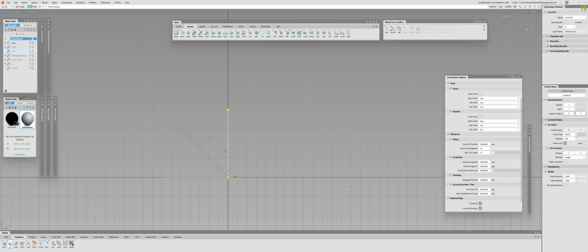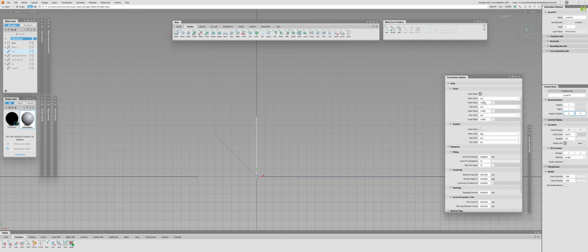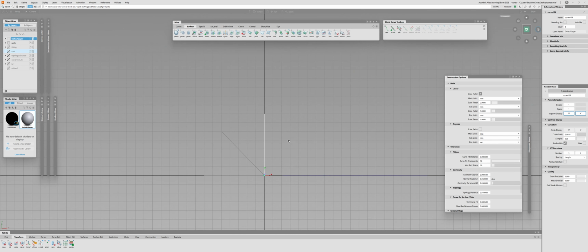The last thing here is the scale factor. It's very simple. The scale factor is basically your multiplier. So you can go lower with 1, for example, 0.1, which means that it will be multiplying by 0.1. So if it would type or move 1 millimeter, instead it will move 1/10 of a millimeter, right? Or you can multiply it by 2, and every 1 millimeter will be 2 millimeters, and 2 millimeters will be 4 millimeters, and so on and so forth.